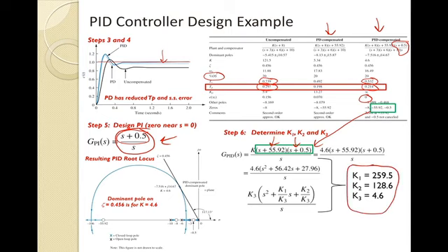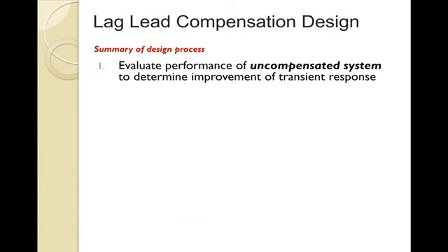And once I have those terms, we could go back to our block diagram realization for GC on one of the first slides of this module. And there's our compensator, our full PID compensator that we could implement for our design. And with that, we say that this design example is complete, and we have achieved our goals of 0 steady state error and a 20% overshoot. Again, we showed you the response. Our goals have been met through simulation, which we're showing here in the upper left corner.